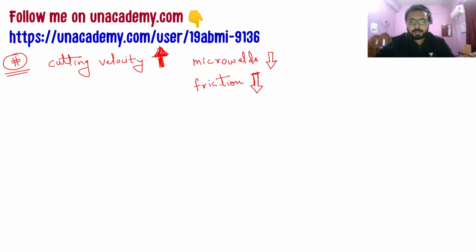So this might get asked in the GATE examination, how these terms are related. So just write this short brief detail that I have provided you in this manner only, so that you can look into it and know what to expect if cutting velocity is increasing. Then what will be the effect on micro welds and the friction. Micro welds are formed due to the high temperature of the cutting operation, again due to the losses of heat that is generated in the form of friction, and that high temperature will lead to some micro welds, which will break or decrease, because they are not able to form because of this cutting velocity.